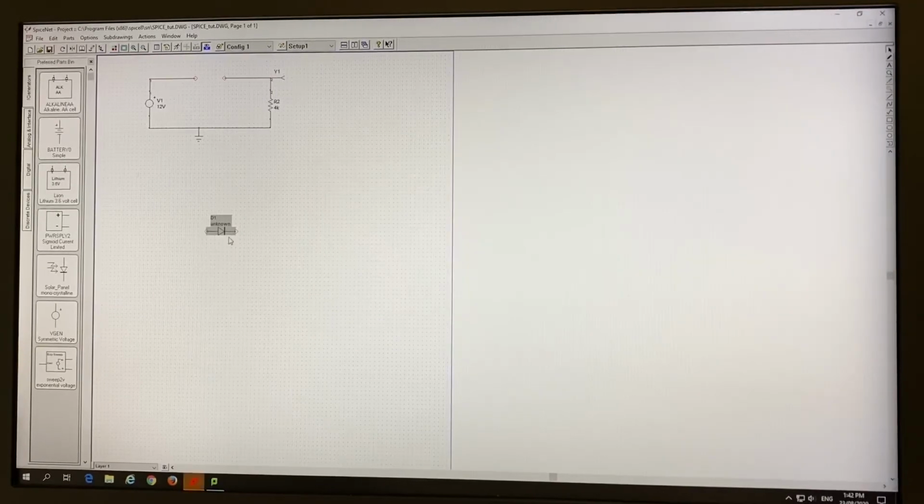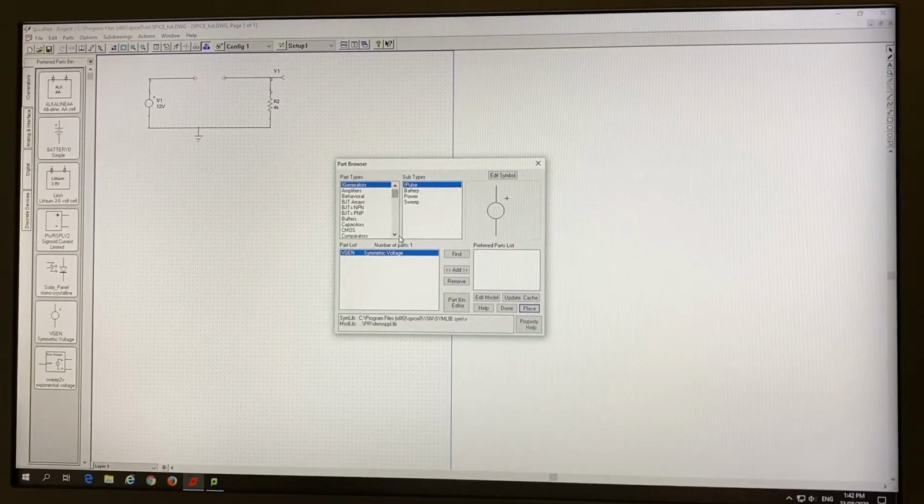So in this experiment, I don't want us to use this one. I want us to go through the long way, and they have a predefined diode already that we can actually find in the lab. The diode we want to use is a 1N4148 diode. So you go to parts, X browser. Then on X browser, we will just scroll till we get to where it's written diode. So I click on diodes.